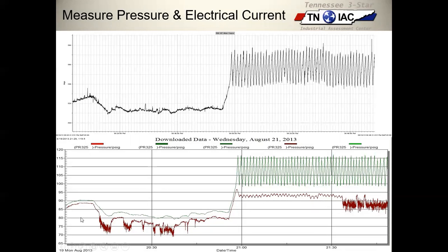And we see this is the normal pressure pattern. But back up here earlier, we didn't have enough compressors. This is running between 100 and say 115, bouncing up and down. This is a controlled band on an air compressor. And we see that this pressure got down to 80 when they wanted it at least 20 psi higher. And so all of a sudden somebody discovers, oh my gosh, we need to turn on another air compressor. And they do, and then we return to normal operation.